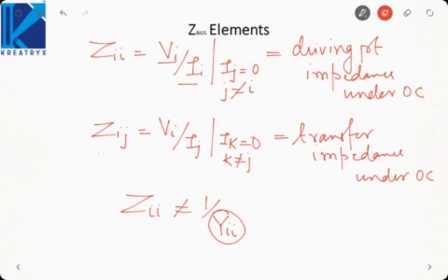And if you have studied Thevenin's theorem, what we do is we open circuit all the current sources and we short circuit all the voltage sources. Then we supply a voltage source at any point and find the current through it.